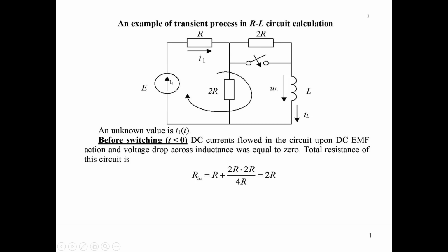It's just an approach which permits you to remember how to deal with inner resistances of EMFs and current sources. It will be just a short-circuited part of the schematic instead of this EMF when it is considered as passive, and it should be considered in the regime when the commutation does happen.